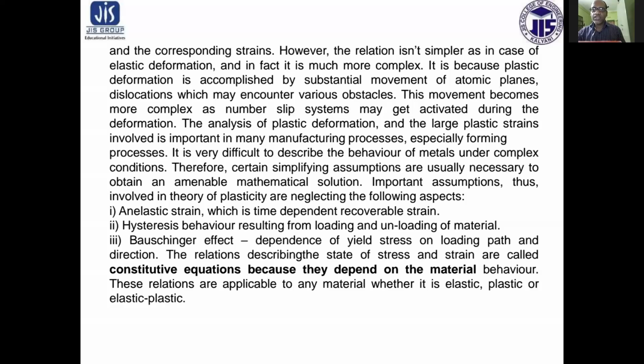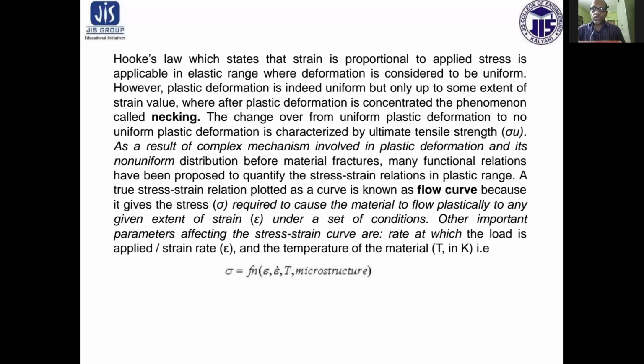So Bauschinger's effect depends on yield stresses, the loading path and direction. The relations described in the state of stress and strain are called constitutive equations because they depend on the material behavior. These relations are applicable to any material, whether it is elastic, plastic, or elastic-plastic. Hooke's law, which states that strain is proportional to applied stress, is applicable in the elastic range where deformation is considered to be uniform.